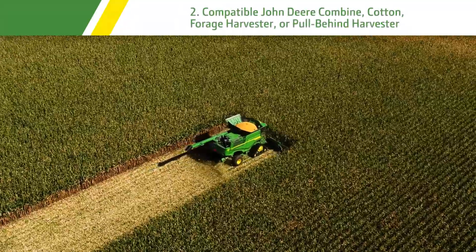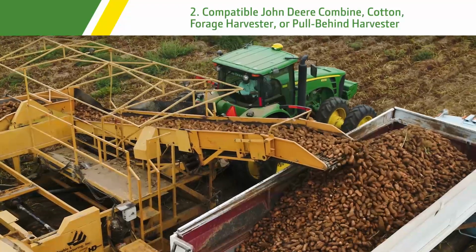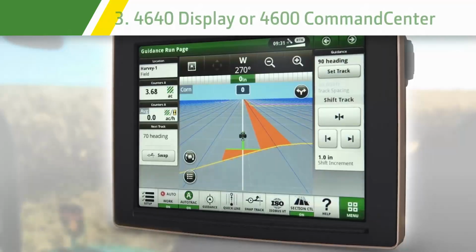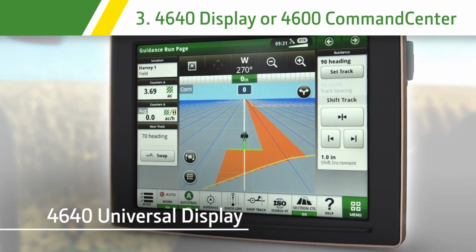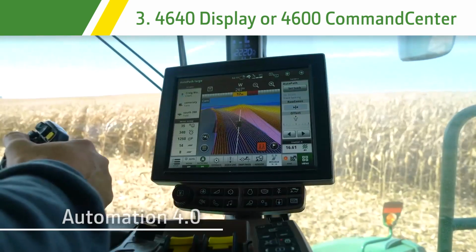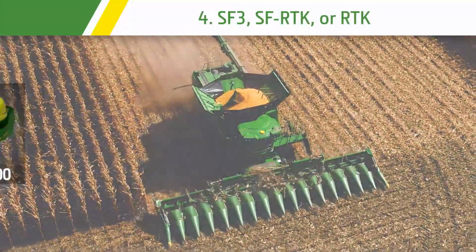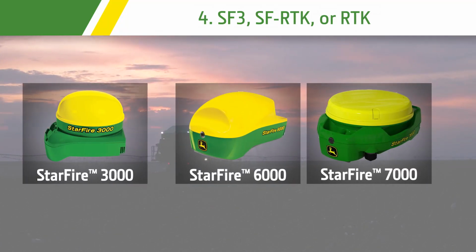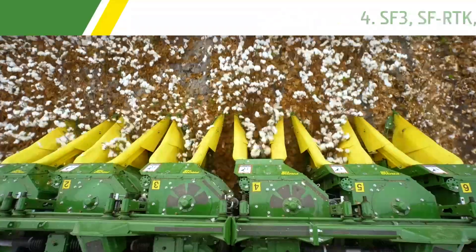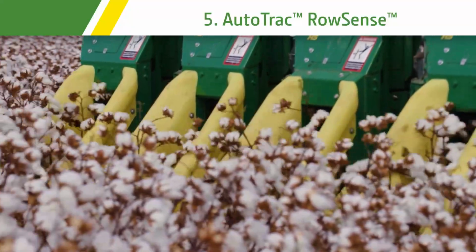A compatible John Deere combine, cotton, or forage harvester with header attached, or John Deere tractor with pull-behind harvester. A full list of compatible machines is in the video description. A 4640 display or 4600 command center with a V2 server and updated display software. The display must be equipped with Automation 4.0. RTK or SF3 correction signal on a Starfire 7000, 6000, or 3000 receiver. The correction signal needs to be the same as the source operation. Lastly, AutoTrack row sense is recommended in conjunction with AutoPath for the best accuracy.